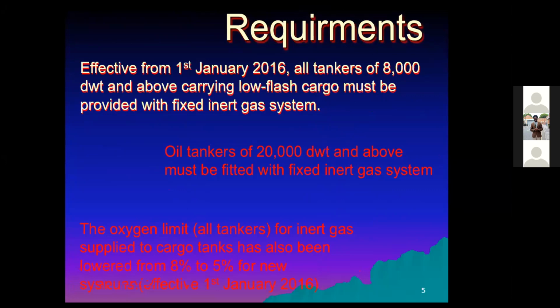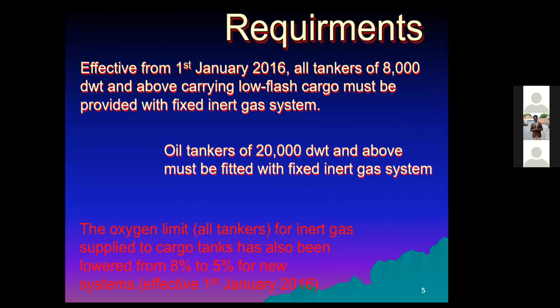Prior to this, as I told you earlier, only oil tankers of 20,000 tonnage and above were fitted with inert gas, but with effect from 1st January, even chemical product tankers or bunker barges that carry low flash cargo must be fitted with inert gas system as part of the fixed fire system.